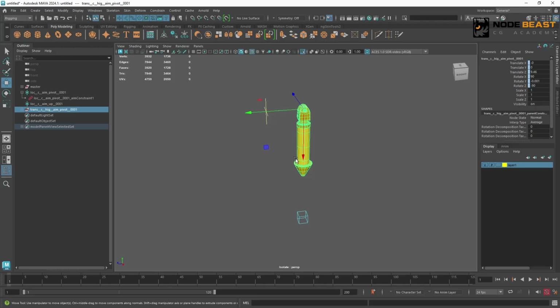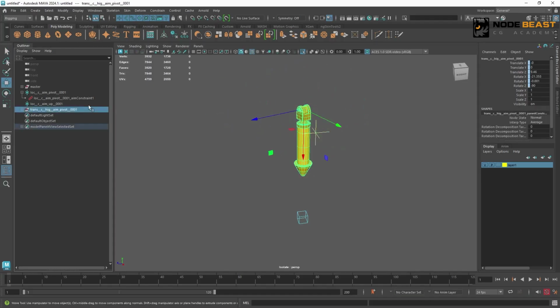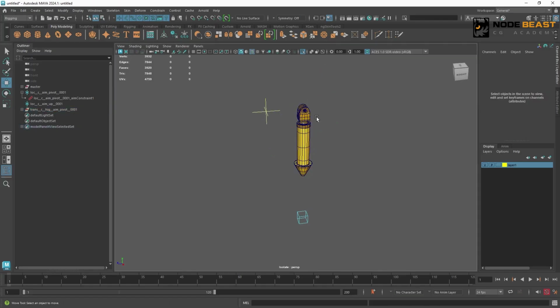The prerequisite is that the first axis always points to the driver object. So here, no matter how we move it, it can only change the other two axes. When we move it to this position, for example, you'll see only the direction of the Y and Z axis changed. The X axis, because it's our primary axis, will always point 100% to our driver object.